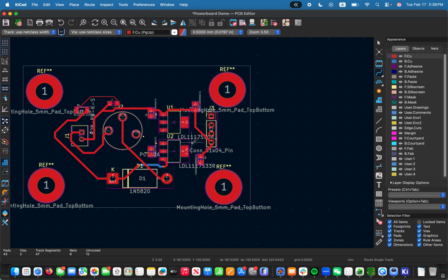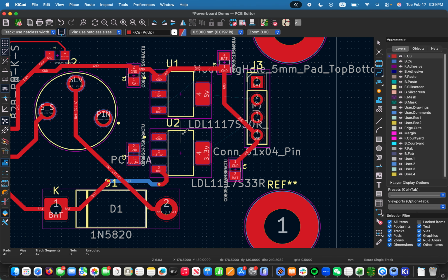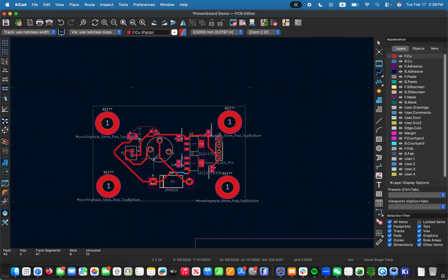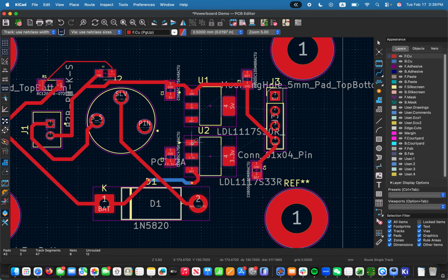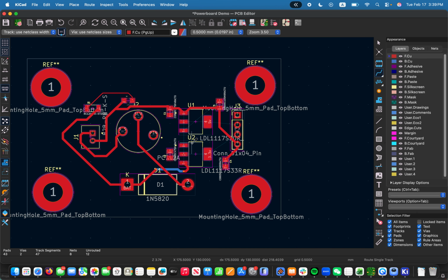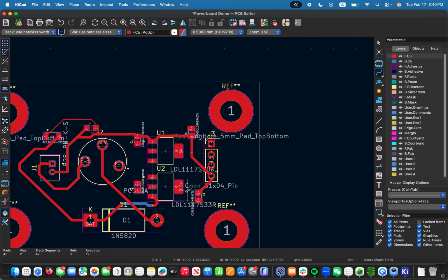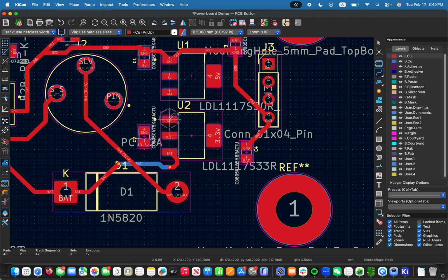So in your actual PCB, I think we are going to ask you guys to do a ground pour, but since this is such a small component, there is no ground pour needed. So a ground pour is basically when you pour in an entire layer as ground, and then you just connect certain holes with that layer. Let's see, make sure all the grounds are connected. I'm going to route this actually this way.